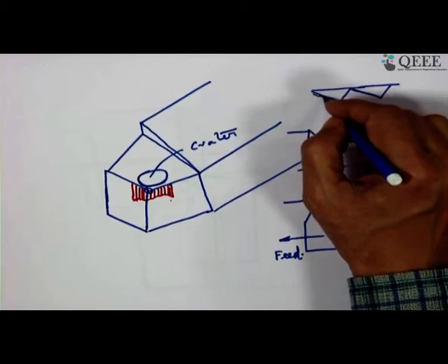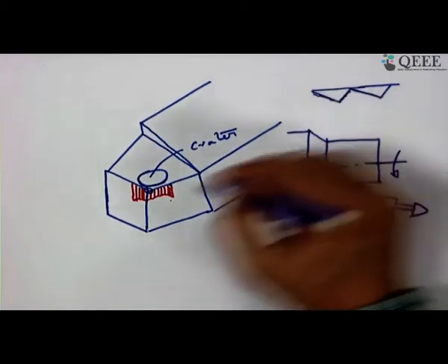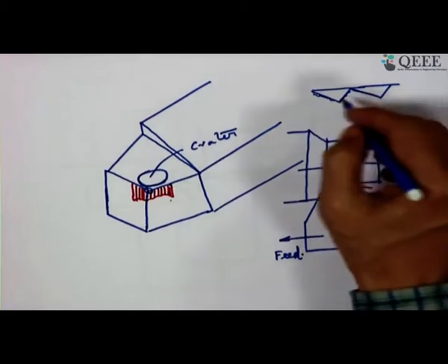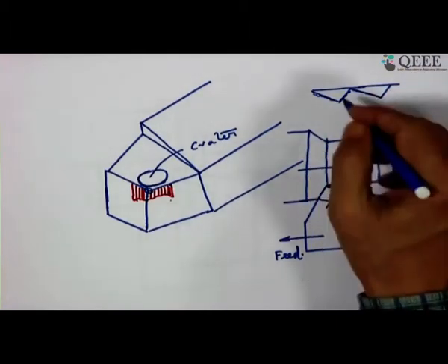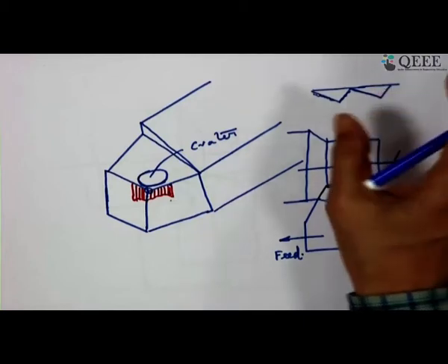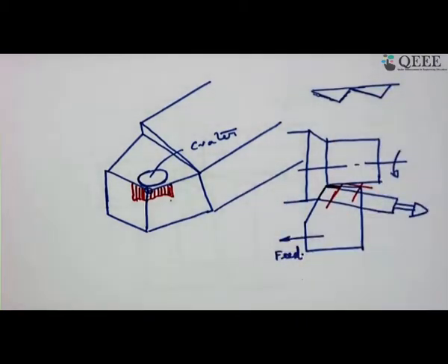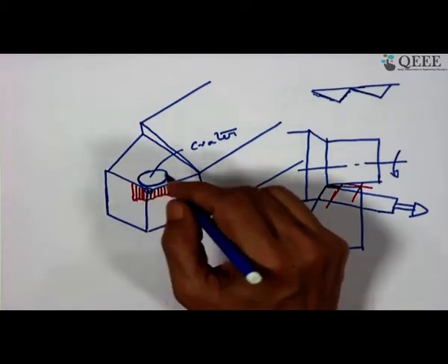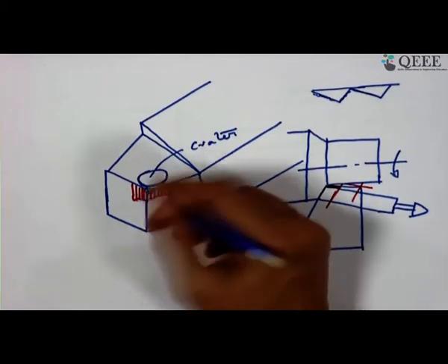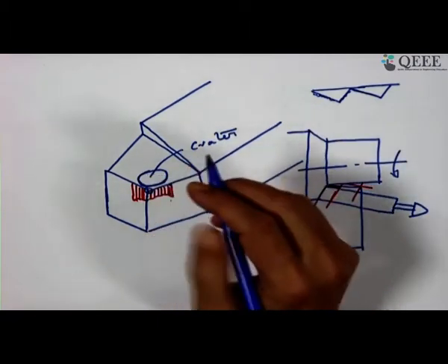If you have this damage on this surface because of this wear on the tool, then your roughness will be more than what we can predict by this theoretical formulation. So, this side will be called the flank wear on the principal flank, this side we call the flank wear for the auxiliary side, and this happens to be the crater.